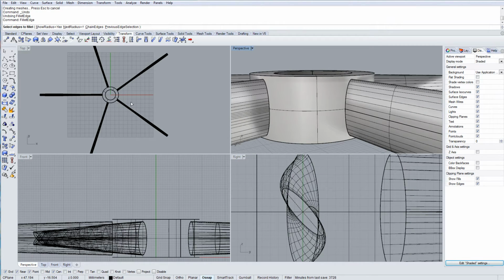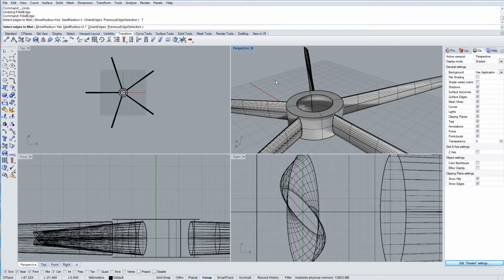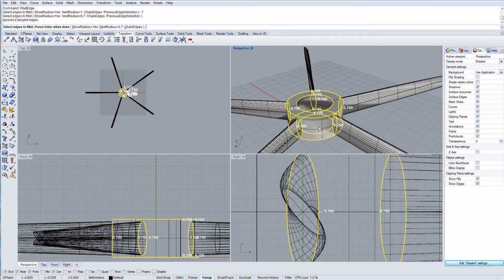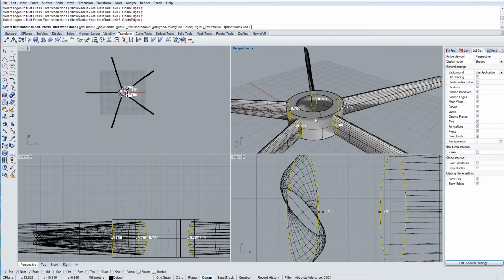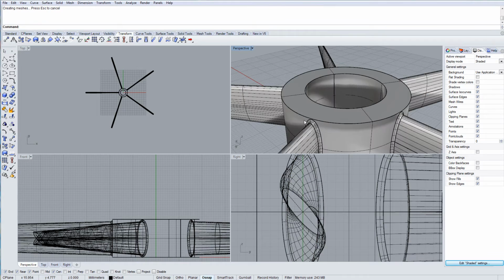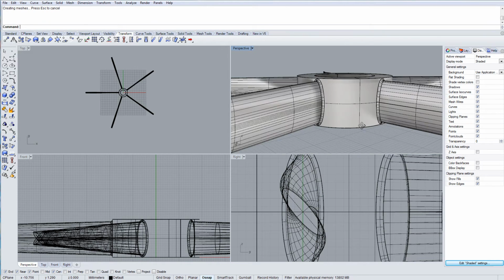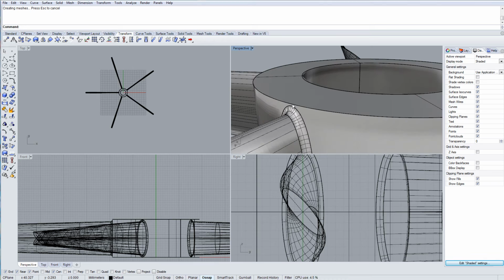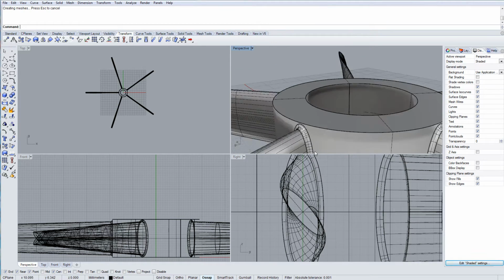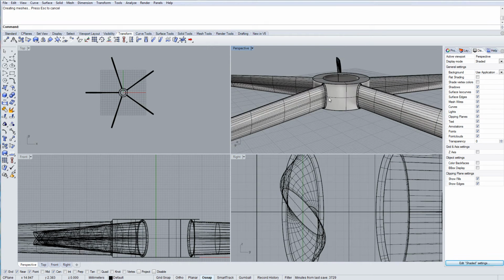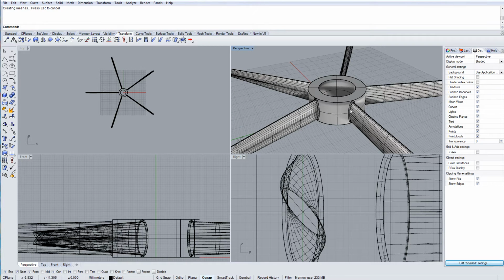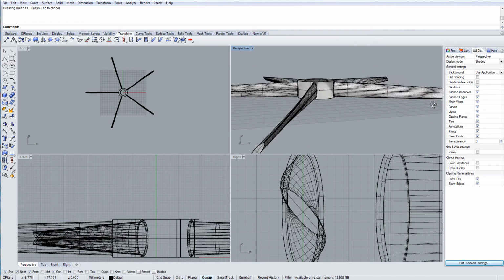So that was 1. I'll do it at 0.7, and again do the same thing. Quite often with fillets, you need to try a few different fillet sizes before you get the right one. I could also make that boss higher. No, that's fine. That's going to be okay. I mean, if I later on wanted to fillet this, I'd be a bit restricted, but I could always extend this edge. It's still a cylinder. I could extend this edge if I wanted a bit more room there. But that should be fine. It should add a little bit of strength to this union here to make sure that it doesn't weaken.